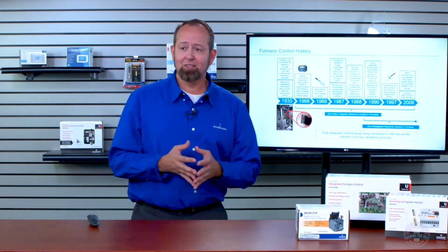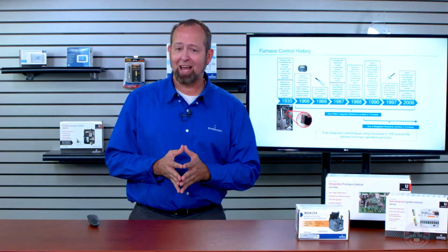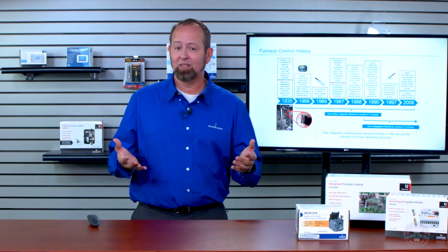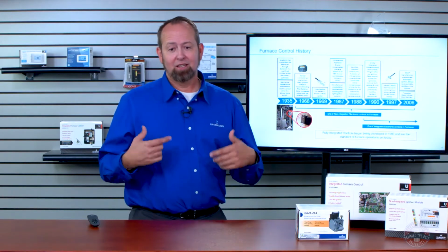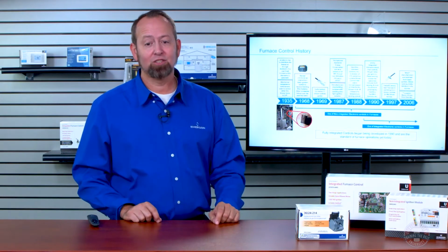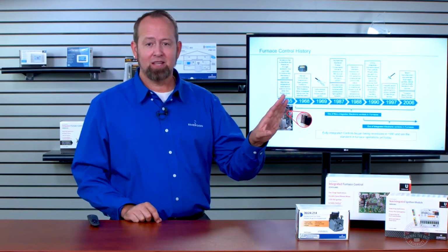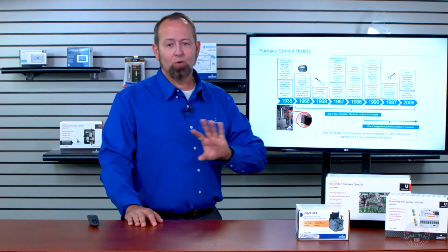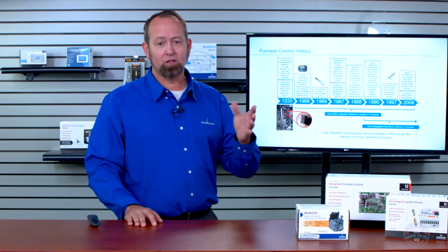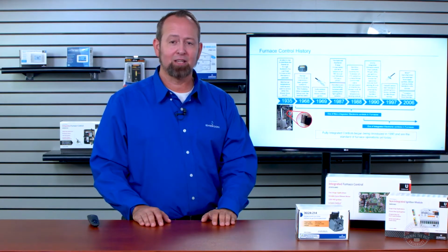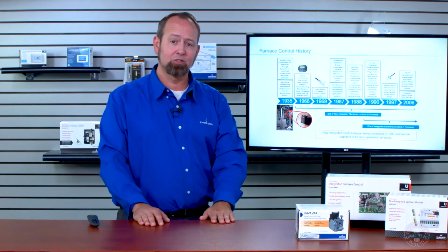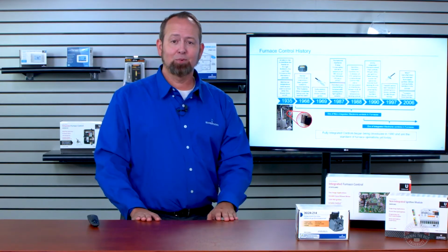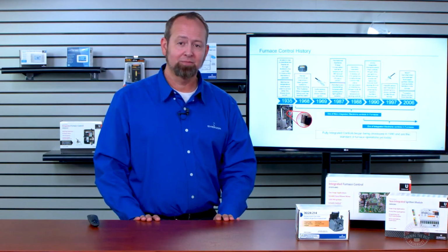That's probably been 10 years or so ago, and chances of that happening are less today with most manufacturers as of 2006 going away from the 80-volt igniters, going away from spark. There is only one manufacturer out there that still predominantly uses spark. Everybody else at this point is using hot surface ignition.